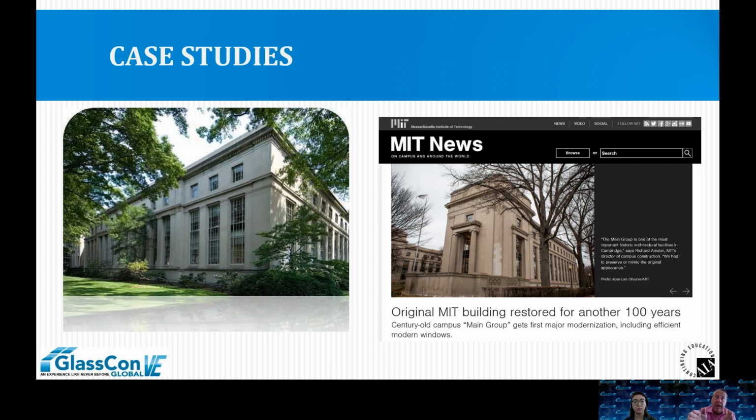In one bay, they did storm windows. In another bay, they reglazed with monolithic glass. In another bay, they reglazed and did thin line IGUs. And in yet another bay, they reglazed and did the VIG. Then every quarter, they did energy analysis and IR scans. They did this really thorough 3-year evaluation and asked, what do we really want to do?